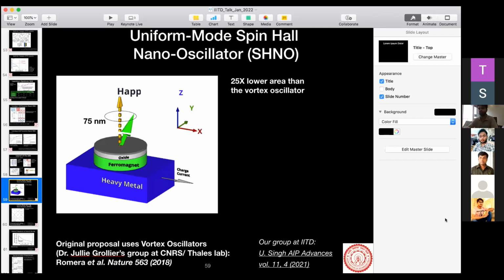But either way, in this magnetic system, if you have a spin transfer torque, what essentially is happening is this: you have the magnetic field like this, and your moment is gyrating around it, you see this green arrow. As it gyrates, gradually it will start to align along this magnetic field because of the damping torque. Now, because of exchange of spin momentum at the interface, the spin transfer torque will work against this damping torque, and it will make the magnet continuously oscillate. And the spin transfer torque is fed by a DC current. Does that now make it an oscillator?